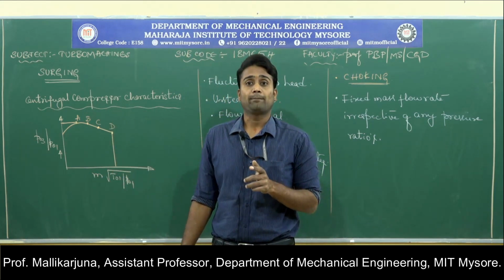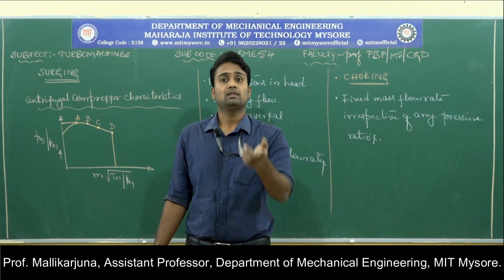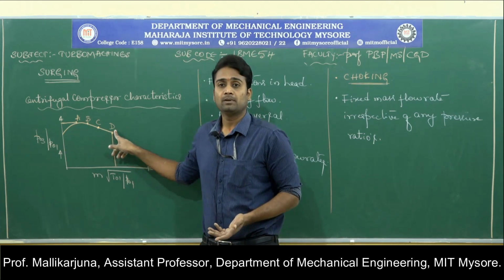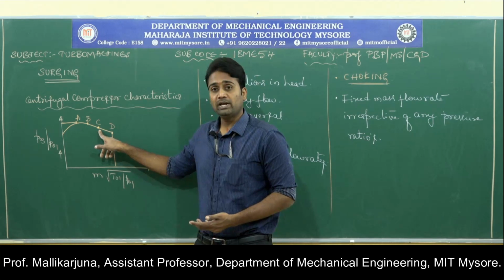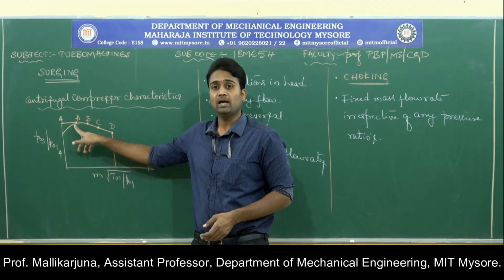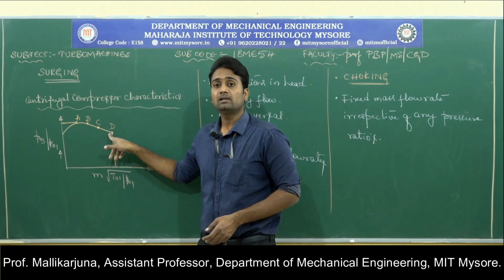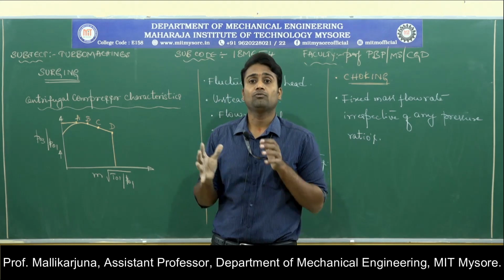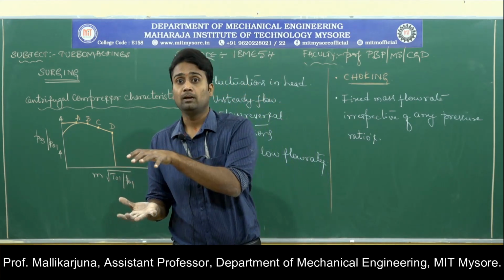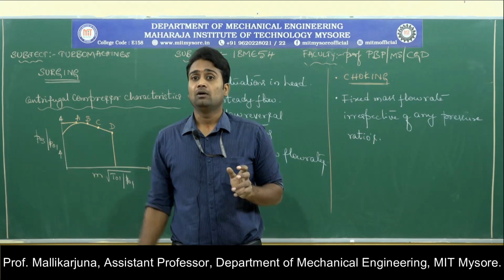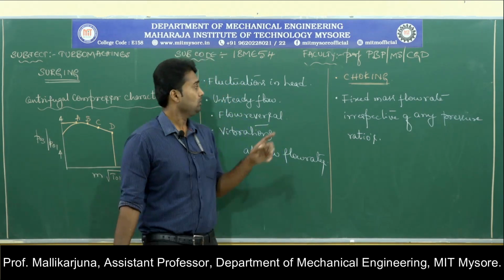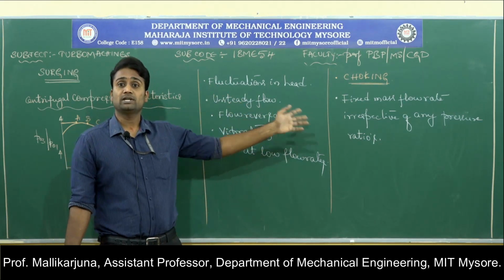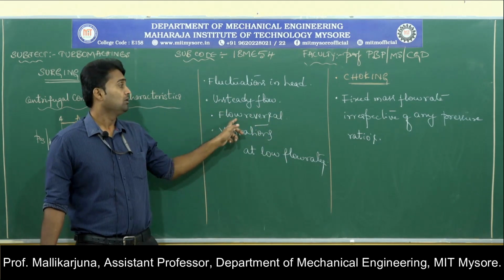So that is what is going to happen, and suddenly the fluid will take the pressure from A to C or D again. Again the same thing will repeat. It will take C, then if I close the valve, B, then A. From A, it suddenly jumps to C or D. So this phenomenon of rising pressures at the downstream because of any irregularities in the flow passage is going to lead to fluctuations or vibrations or unsteady distribution or unsteady delivery or flow reversal.